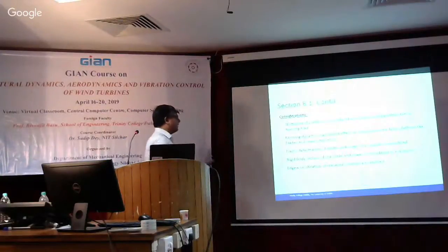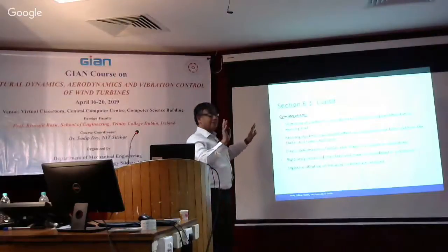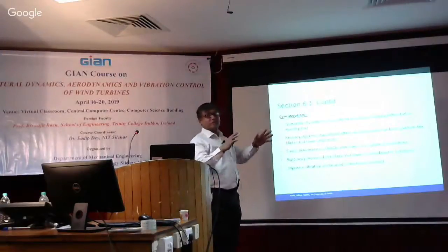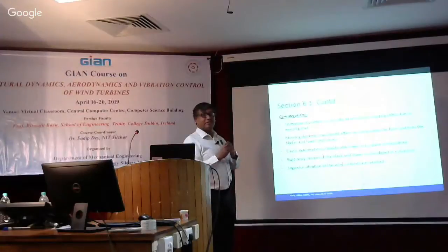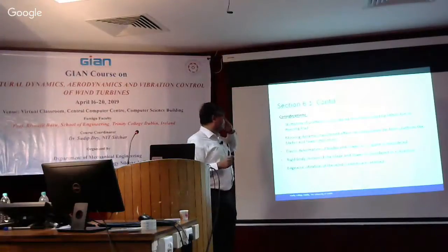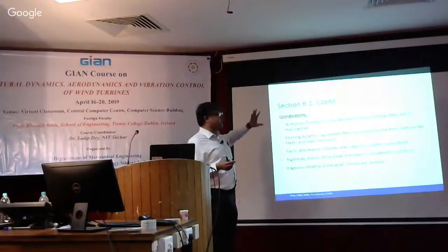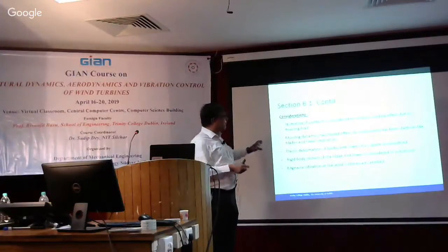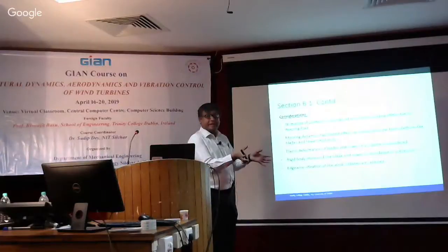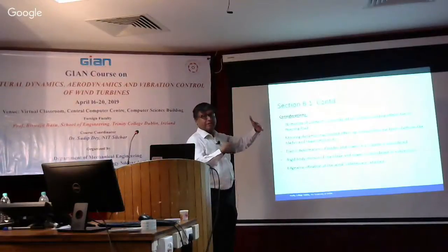But in a simple way, if you just don't consider the effect of the fluid on the structure, the fluid-structure problem, because then you have to solve the PDEs, of course, then what you simply do is take the ODEs, as I've said, and then take the mooring cable as an equivalent spring, and then you have a set of ODEs to solve.